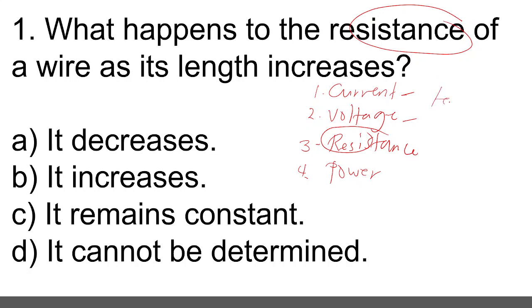First is the length, and the second is our AWG number, right? So on this part, we have length, wherein you have to understand that the longer the wire, therefore it increases its resistance. Why? Because when the path is long, the flow becomes slower or weaker. In some cases, there are many obstructions or obstacles the electricity may pass through. So the longer it is, the higher the resistance. Longer, it increases the resistance.